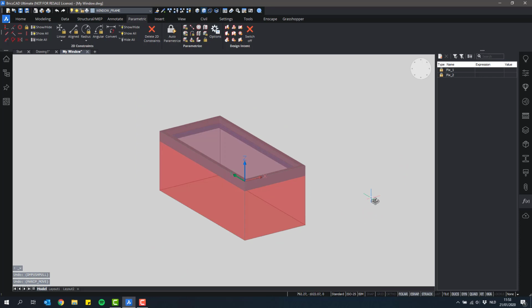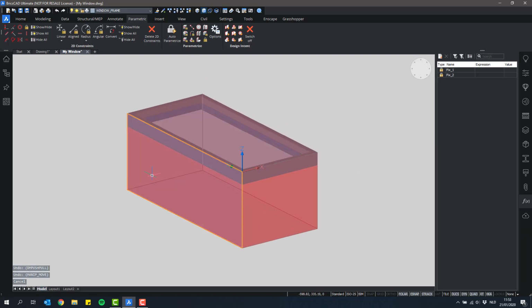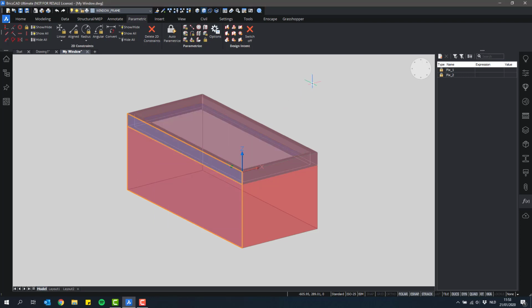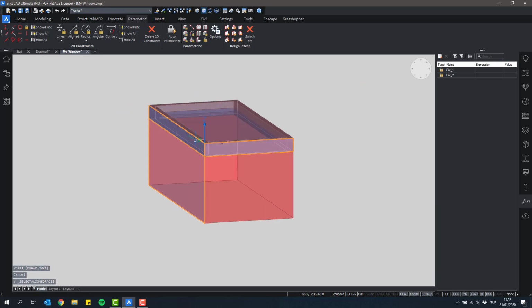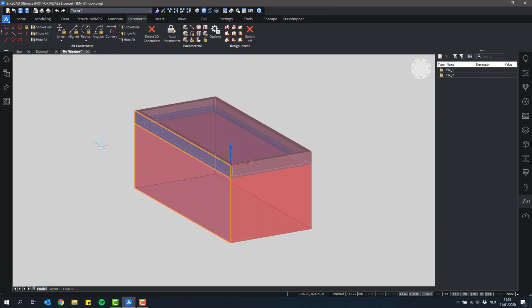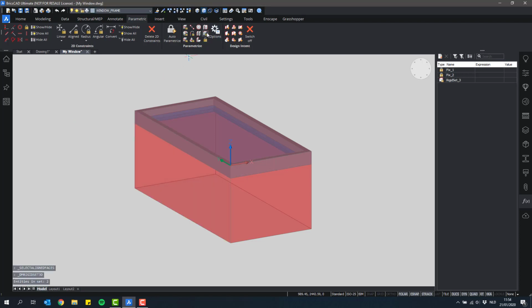So what we want to do is create a rigid set that connects this face and this face here. The easiest way to do it is to hover over the side face of this subtractor solid. In the Select tab, there's a thing called Select Aligned Faces. If I click this, it will now also select the other face, the other face that's aligned with this face. I have these two now, and I can put them in a rigid set. I can either right-click and in the quad, under Constrain, click Rigid Set, or I can use this rigid set option in the ribbon here.